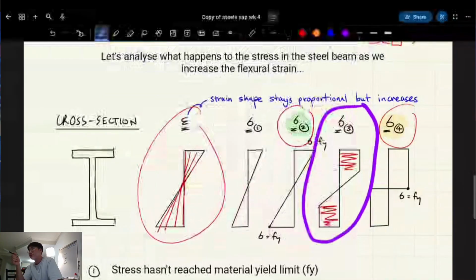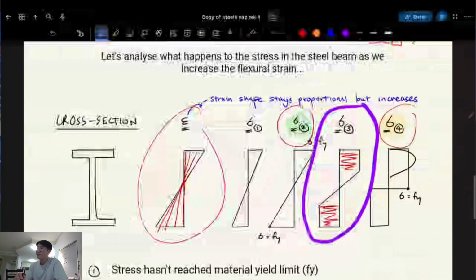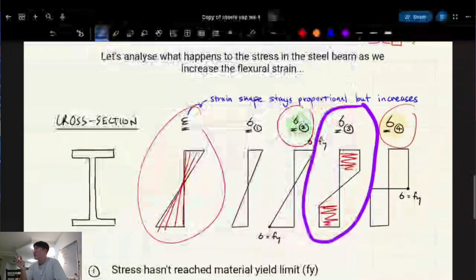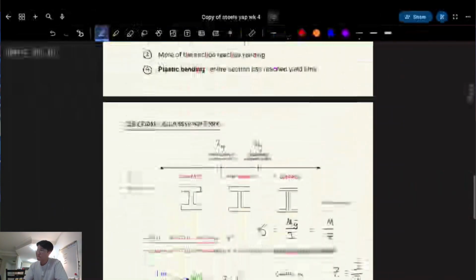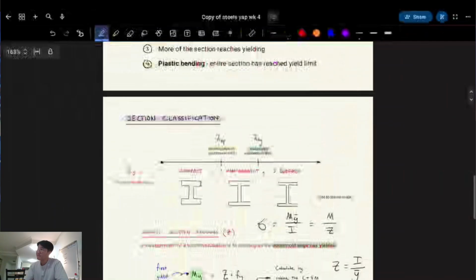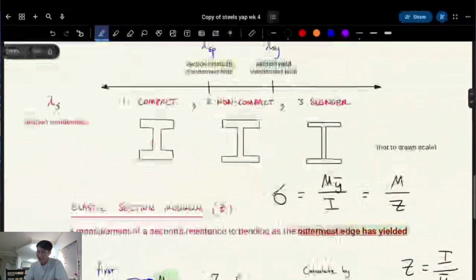Because once you get reinforced concrete, the material curve for concrete looks like this, a parabola, for the compressive side. So you can't use that equation anymore. It's only for unreinforced concrete, and the moment it cracks, that's called the cracking moment. You can't use that formula anymore. That formula is like saying y equals mx plus b.